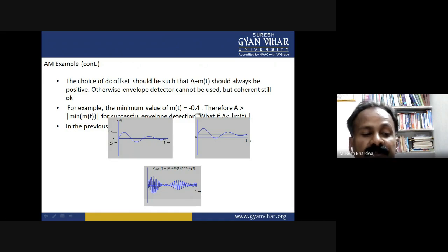So, the standard equation for amplitude modulation may be expressed as x(t) cos omega_c t plus A cos omega_c t. So s(t) equals (A plus x(t)) cos omega_c t. According to the equation discussed, we are seeing the modulating signal, baseband signal, and carrier signal.